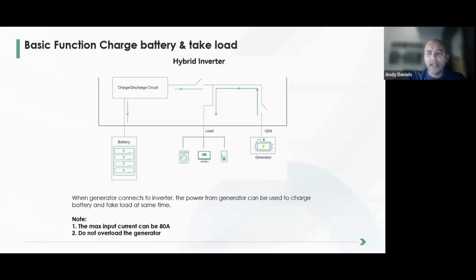And this is also an important thing to explain to your clients, and each one teach one. So the knowledge sharing goes like this: your generator, as you know, has an alternator that puts out power, and most generators will have a voltage regulator on it as well. Once the generator starts, you will need the automatic voltage regulator to settle down so that it can put out the right voltage, number one, and the right frequency. So this relay here will not close until those requirements are met.